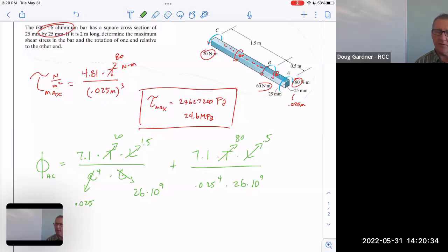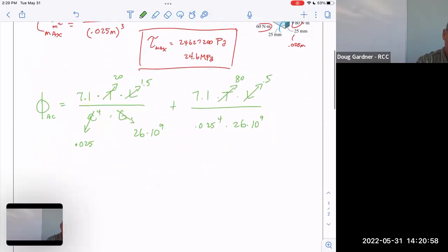Again, not obvious. I can't remember if I got this wrong the first time, but you know, the temptation is to just say, oh, it's all the way across. But remember, twist is torque and length. It makes sense why you'd have to do both of these separately, because the twist of those 2 is not the same. And because it's not pinned on either side, the twist from A to C is found by adding up both chunks individually. So if you don't screw this up, from A to C you get 0.0489.